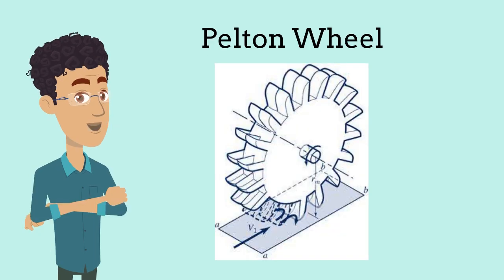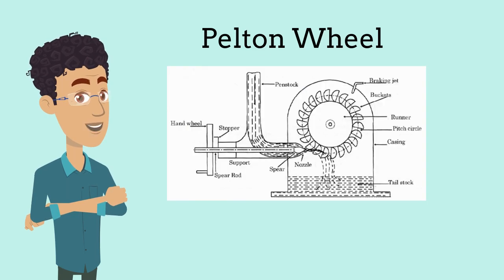Although they follow the same principle as the steam turbine, the turbines used in hydroelectric power plants have a unique design, named Pelton wheels. These turbines consist of a circular disc, also known as a runner, with several metal buckets along its circumference. The water from the reservoir flows into a nozzle used for flow regulation. From the nozzle comes a jet of water, which causes the movement of the turbine, resulting in the production of electricity from its shaft work.